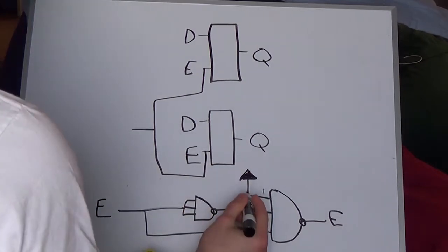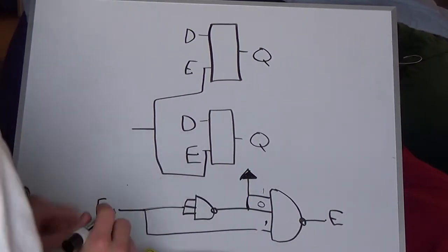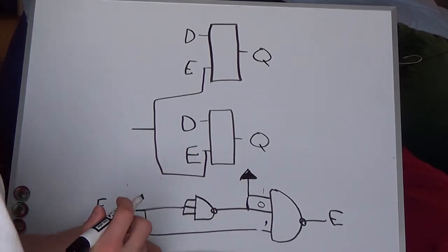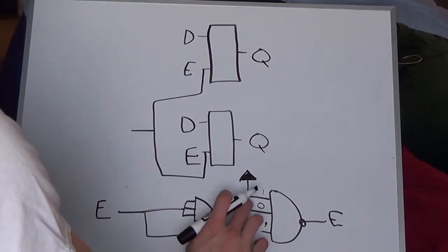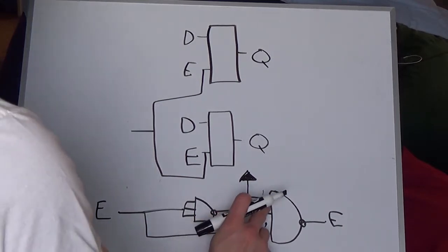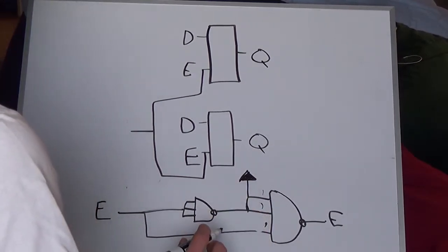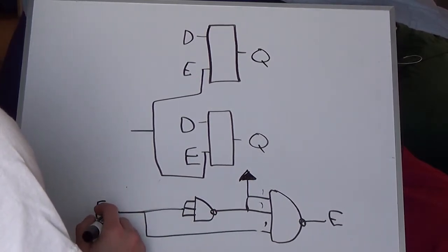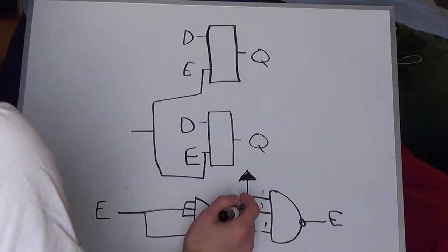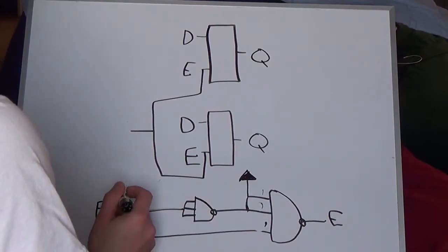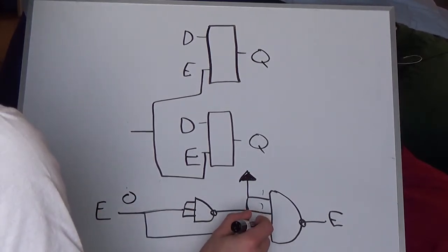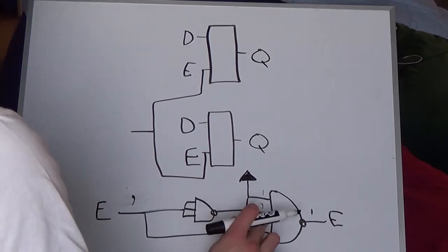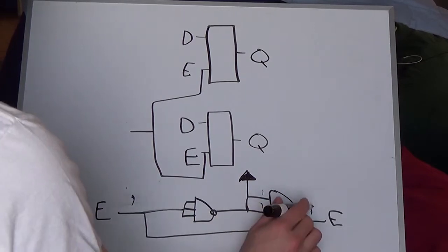So as a fix to this, I tied this input, well, output of this inverter, input to this 3-input NAND gate, to power. And so now both of these are always 1. And this is simply an inverter. It doesn't matter what goes into this. This is always high because I have it pulled to power. If I put a 0 here, this will be high. If I put a 1 here, this will be low.